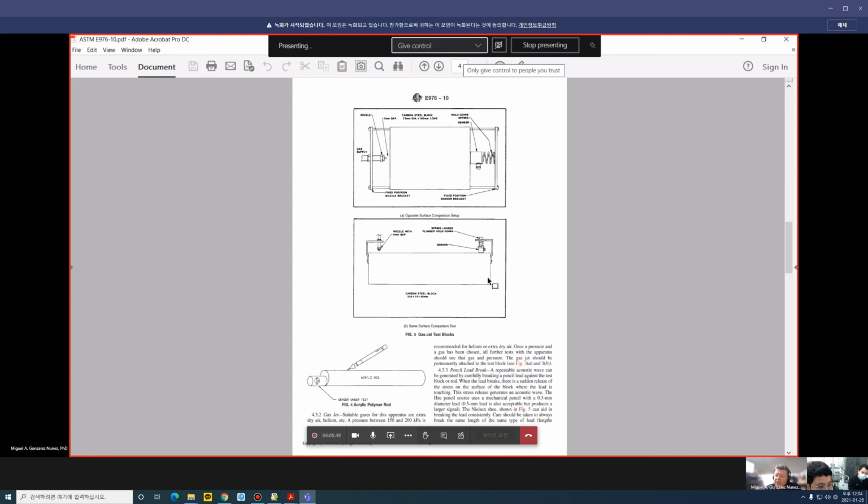I don't know how you are holding the sensor to your test piece. With a strap. You mean how to attach the sensor on the specimen? Yes, how to hold it in place, because you are not using a couplant. Yeah, with wax. Using wax. Okay, that is your couplant. Yeah, that is kind of my couplant.